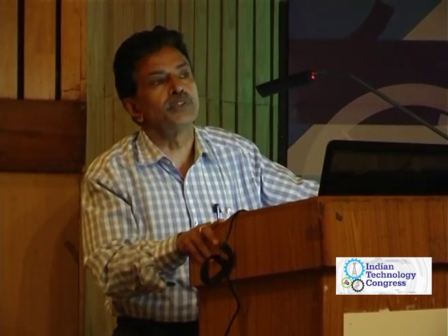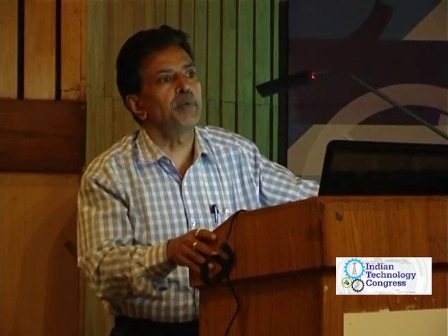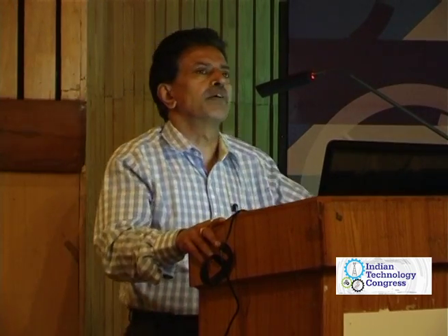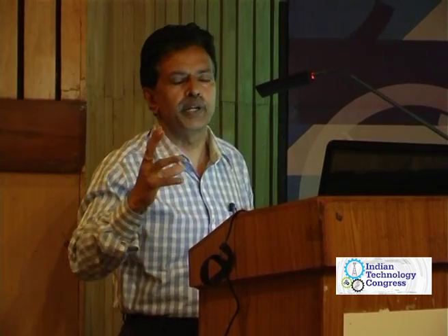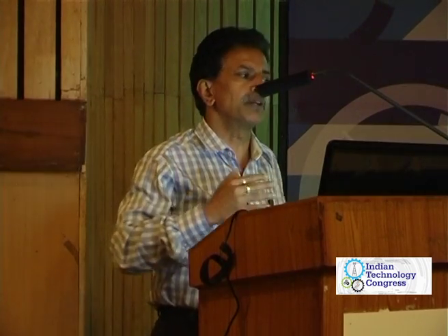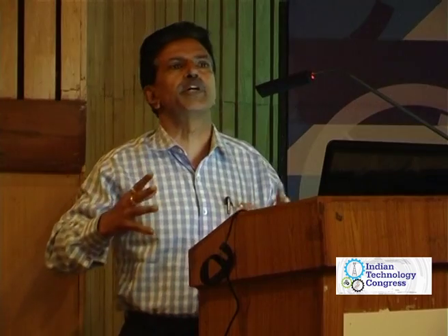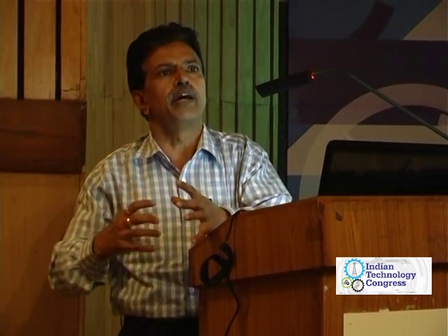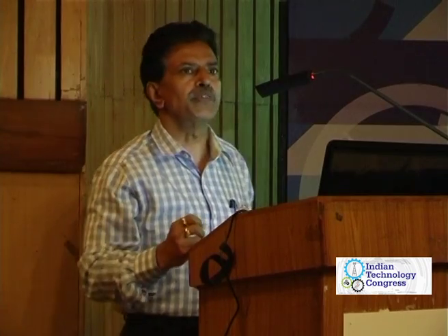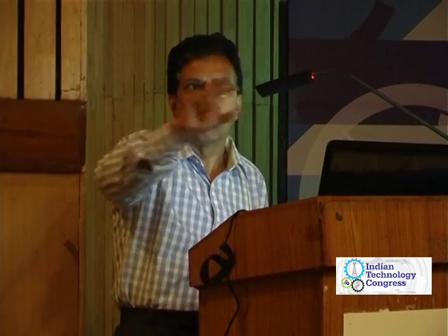and come out with the right quality product. Because at the end of the day, experimentally from the past 3-4 years, I have been struggling to optimize the extrusion temperature, the billet temperature, the die temperature. If there is a huge temperature gradient between my billet and my die, it's going to be very difficult for you to get a quality extrude. Because the surface finish of my extruded product is very, very important.